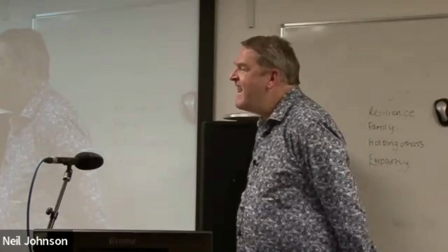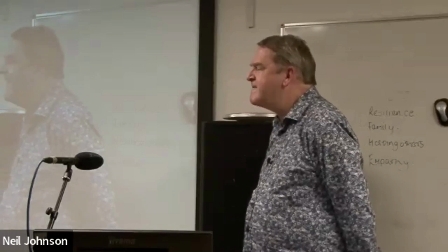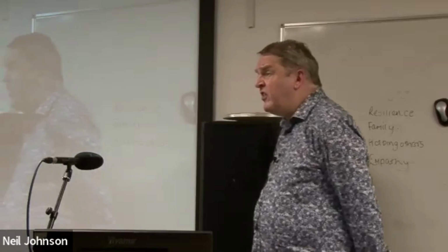Some of the old Fenders used quite undersized output transformers. Okay. That lost bandwidth as they started to saturate, right? Which had an effect of imparting a different tonality to the tone on overdrive than when it was running clean. Okay. Which could be seen as an advantage. Right. So the same principles could be applied.